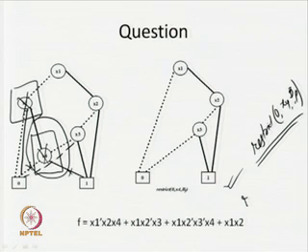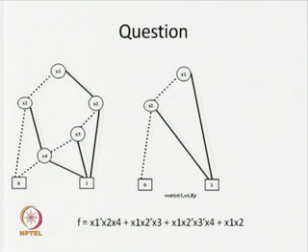Now, similarly try to construct the BDD for restrict 1 x4 of f. So, in that particular case what will happen? Similar rules we are going to apply. What we are going to do? We will remove this x4, and whatever incoming edges we have will be redirected to the 1 edge of this x4. So, that one will straight away come over here and this dashed line will come over here. So, we are removing these things. Whatever resultant BDD we are getting, it may not be a reduced one.